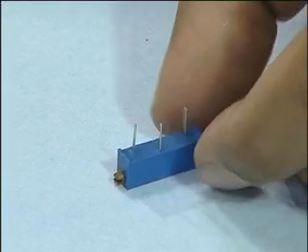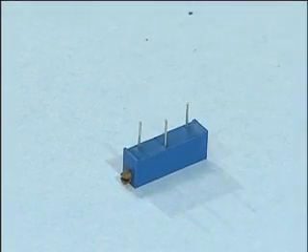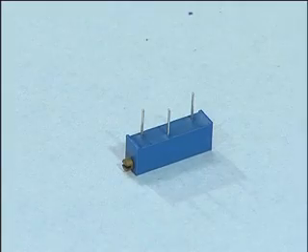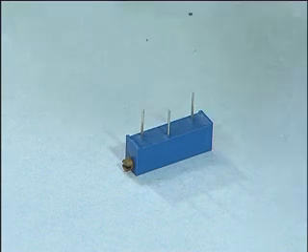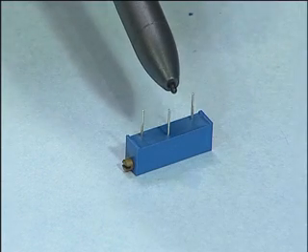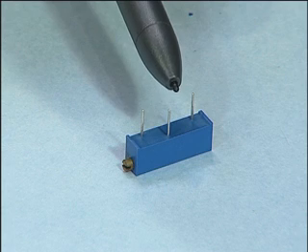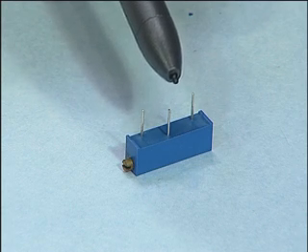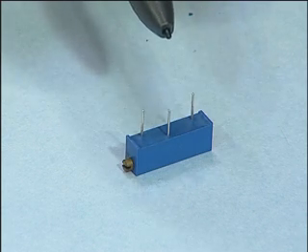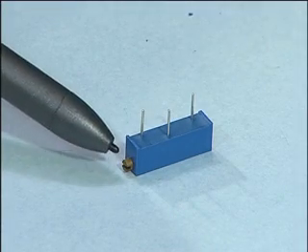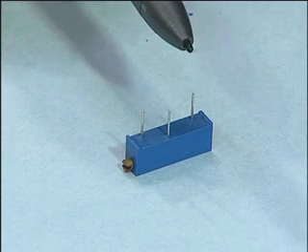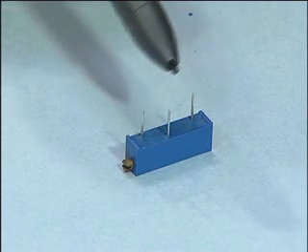There is another type of resistor here, slightly different from the type that you saw. This has 3 terminals. This is a variable resistor, just like we saw in the symbol, 2 terminals and an arrow in between. It is that component. You have 2 terminals, and the third terminal is the tap which represents the arrow, which varies with respect to either of the 2 terminals.